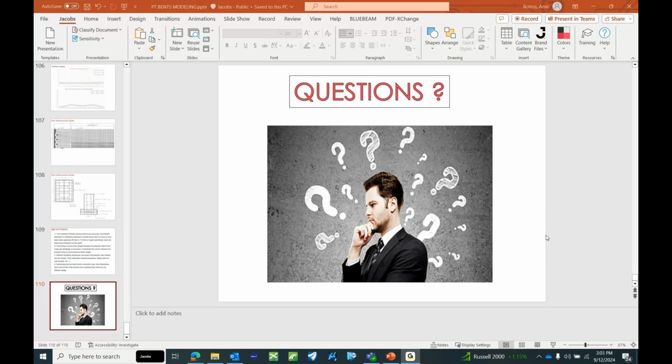So the Bailey trusses, I have not actually included the stiffness of the Bailey trusses. I only included the stiffness for the rubber bearings that are meant to be supporting the formwork during the pour of the formwork. Because we were assuming that this bent is going to be sitting at the two ends on some sort of jacking system or height adjustable system, and in the middle will be sitting on the rubber bearings, I did not bother to include the stiffness for the trusses. Of course, doing this is going to be more accurate for the analysis for sure, but that is just my assumption for the design of this bent.